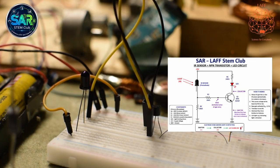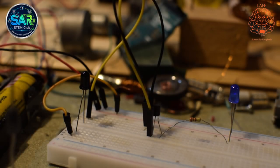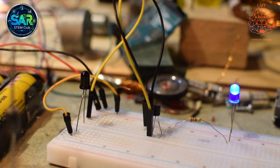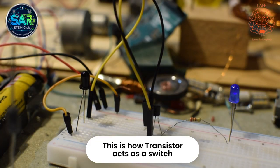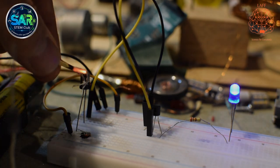Now I'm going to switch off the lights of the room and bring the matchstick in front of the IR sensor. You can see here I'm bringing the burning matchstick, which emits infrared light. Whenever I bring it in front of the IR sensor, the electric current moves from positive to the negative side, and it goes to the base of the transistor, by which electric current goes from the collector side to the emitter side of the transistor, and the loop completes and you can see the LEDs glowing.